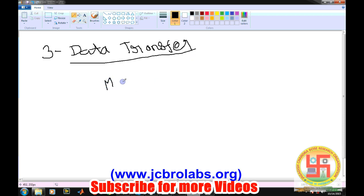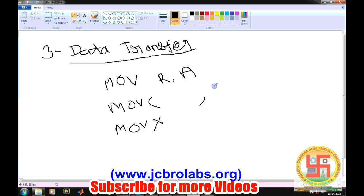The most famous operation is MOV. It transfers data from any register to any other register. Similarly, as we just discussed, MOVC moves from a ROM location and MOVX moves from external memory. Other than that, we have XCH, which is used for exchange purposes, so the contents of the two registers are exchanged.